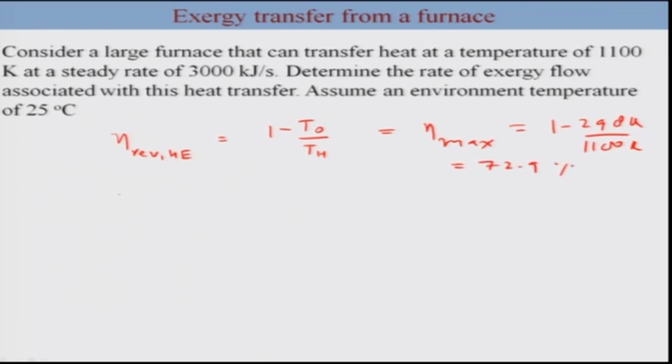Okay, that means this particular reversible heat engine can convert 72.9% of heat in from this furnace to work. Which essentially means that the exergy of this furnace is nothing but equivalent to the power produced by this particular